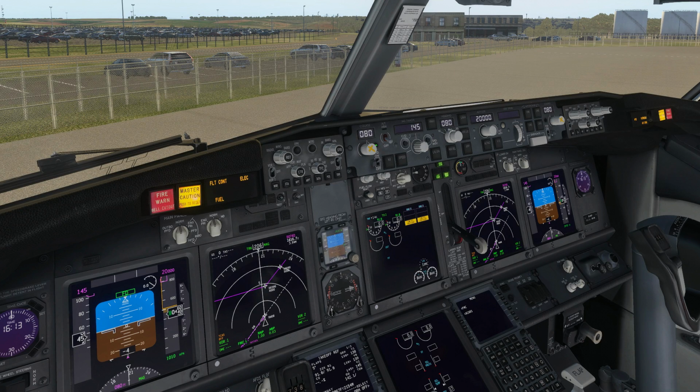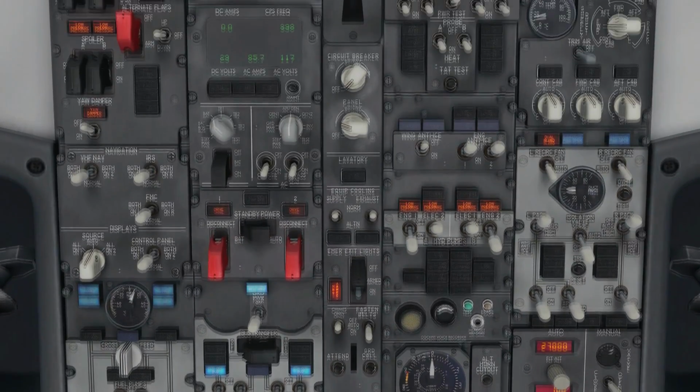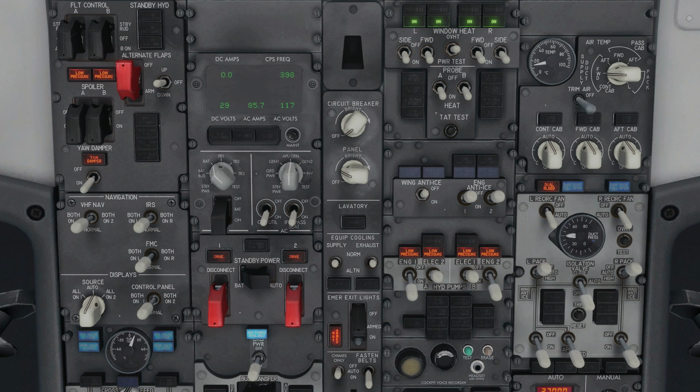So we'll go flight directors are on, auto throttle off, IS max selector V2 plus 15, but we've got that set, so let's check. Altitude, our cruise level, we're going to 37,000. Check. After that, we've got our fuel flow, reset rate, minimums, we'll just say set. Landing gear down, speed brake lever down, thrust levers closed, start levers cut off, and yaw damper on if IRS is aligned, which it is, so we can turn that on. That is the pre-flight procedures.